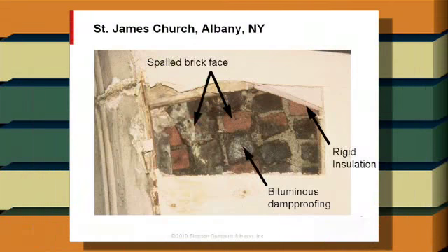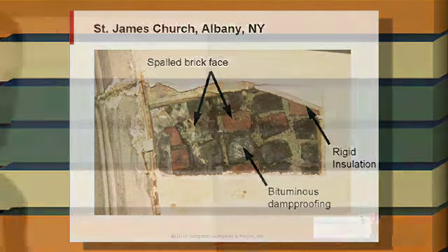And so this is, when I took this apart, you can see this terrible picture because it's scanned from an old photo. There's some rigid insulation here, extruded polystyrene, good vapor barrier, and then the brick is starting to spall. This is a view from the interior.